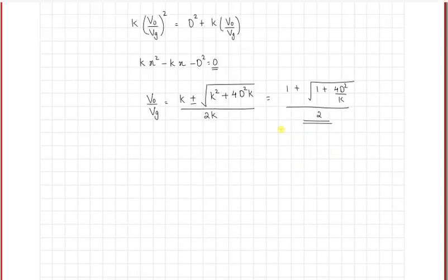Right, so that is the expression for the voltage gain in terms of all the converter parameters and duty ratio. Right, k is not like d2. Once you know the values of L, R and Ts, you can calculate k, and so you can straight away get the value of V naught by Vg.